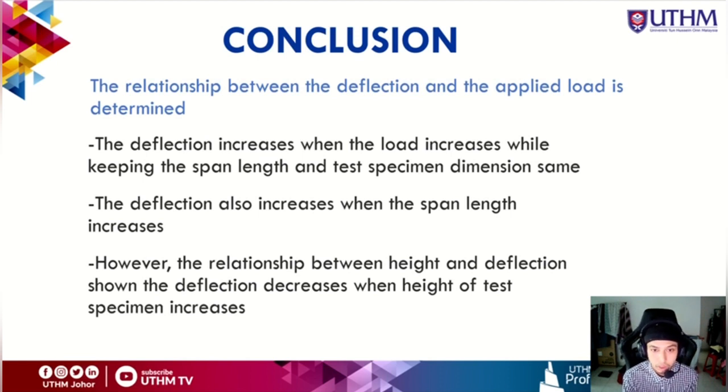For the conclusion, the relationship between the deflection and the applied load is determined. The deflection increases when the load increases while keeping the span length and test specimen dimensions the same. The deflection also increases when the span length increases. However, the relationship between height and deflection shows that the deflection decreases when the height of the test specimen increases.